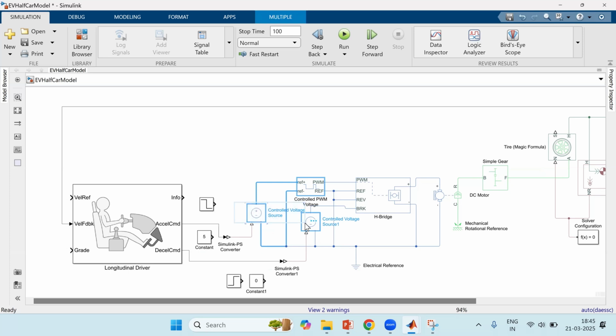See, actually in your house, how are you controlling the ceiling fan? By your regulator, right? Yes. Similarly, we are trying to model it as a regulator. So here we will generate a maximum of 5 volts. If we generate 5 volts, then the PWM is intended to reach 100%. If you reduce the 5 volts, then the PWM reaches 0 volts, 0%. Okay, sir. Yes, sir.